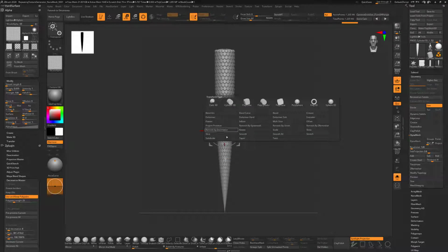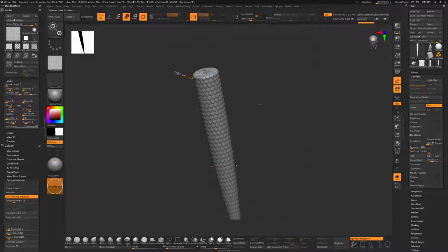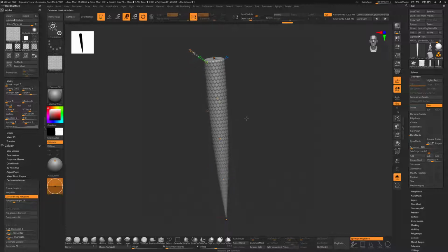And the last one I'm going to use is, there's a bend curve, and you can tell it which direction that you want it to bend in. And if we hover our cursor over this thing, this is symmetrical, we don't want that axis. I'm going to change the axis, and I'm going to click and drag it to where it says 2, and now I should have a dot on the top and the bottom. The blue one here is smooth. I need to find the resolution of this. So curve resolution, I'm just going to click and drag this to 6. So that's going to give me a few different points.